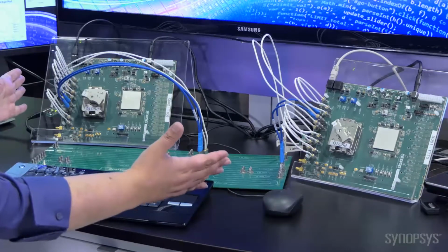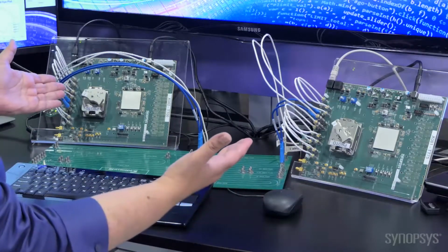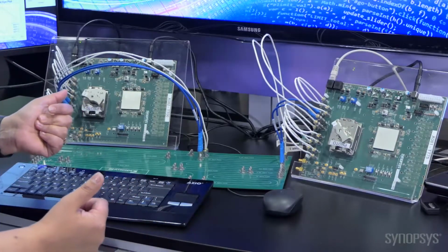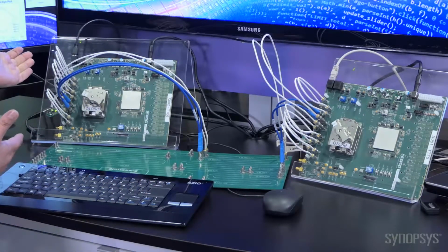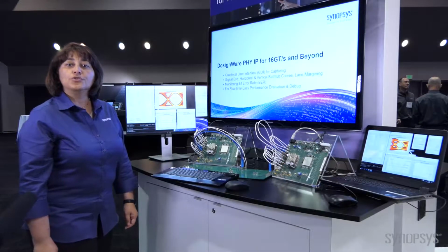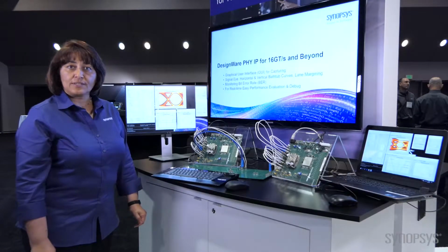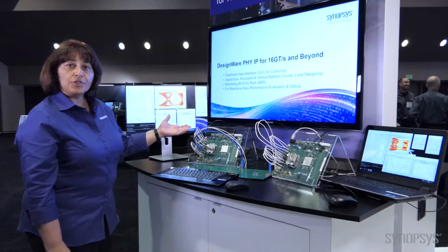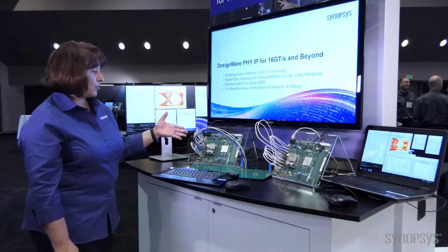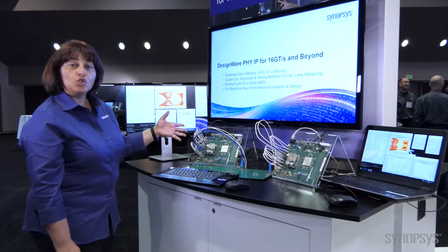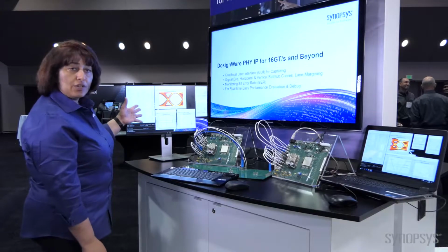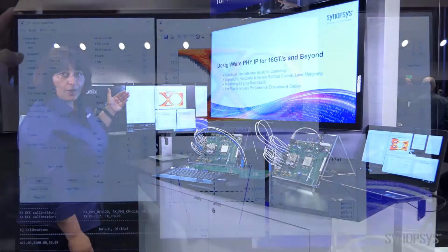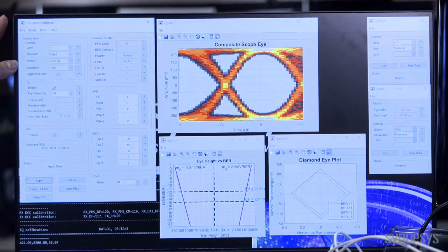Now, this demo can be used and verified by using a very flexible user interface that we'll be moving to demonstrate. Let's walk through the graphic user interface that allows this interoperability to happen. So we're first going to configure the 16 nanometer evaluation card to transmit using the GUI interface. Right now we are trying to transmit PCIe Gen 4 with PRBS 31 pattern.